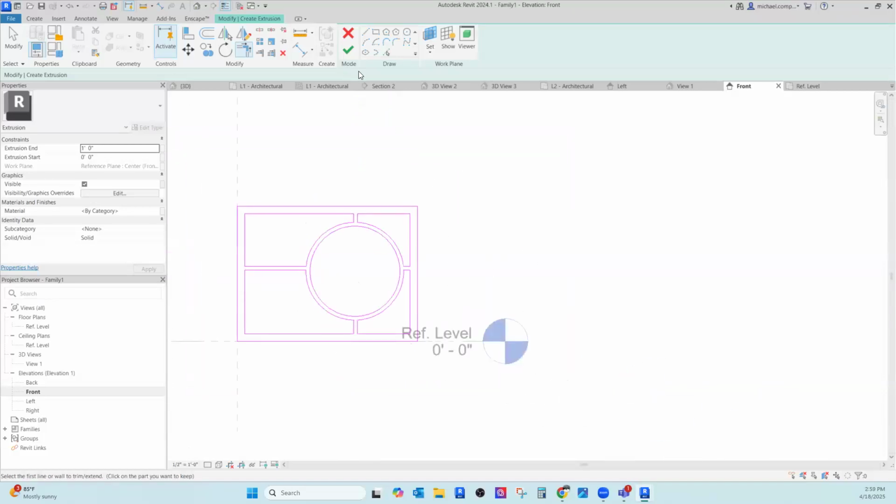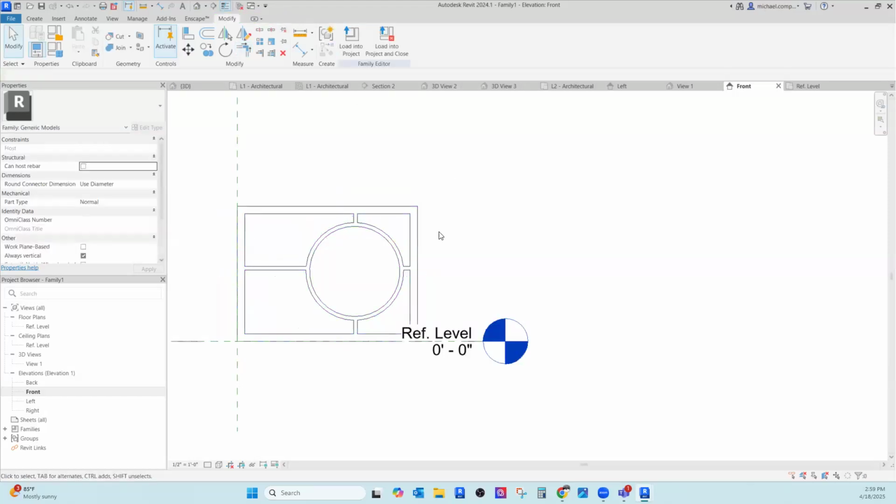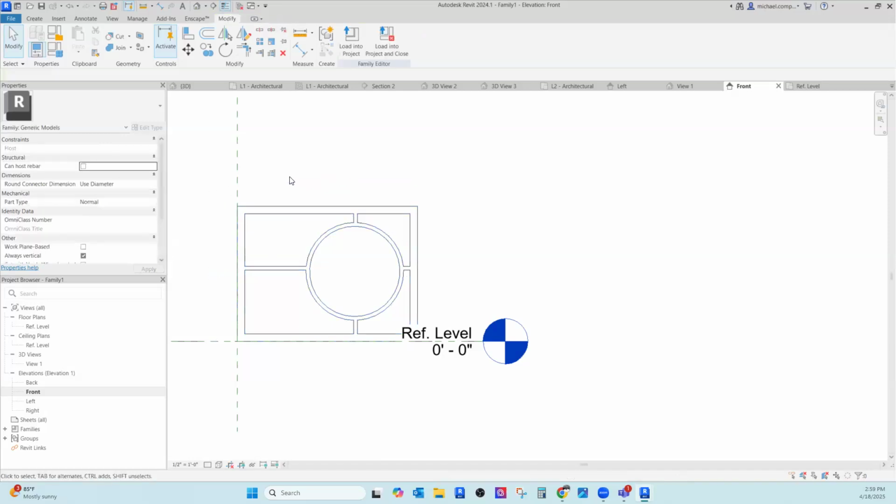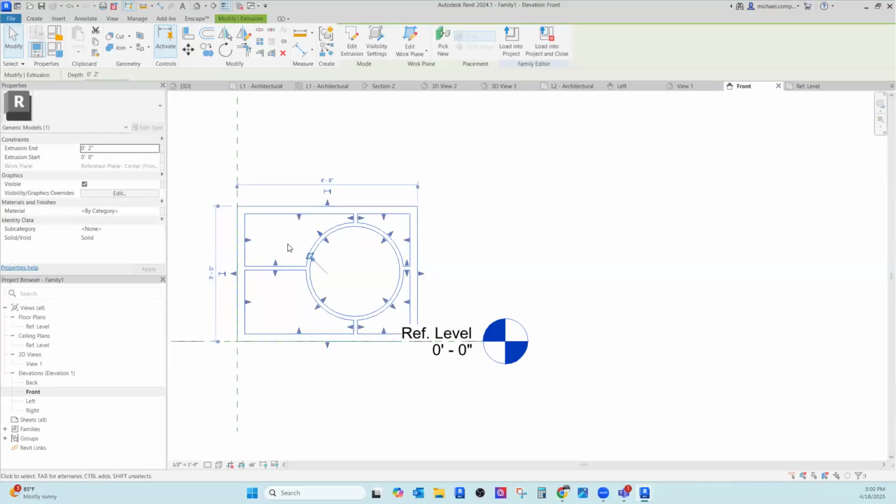Okay. So there's my custom panel, railing panel, right? So hit OK. And that's just the structure of the thing. Now I need the, oh, by the way, what did I say it was? It's not a foot thick, that's for sure. Let's make it 2 inches thick. And then I need the stuff in the middle, right? Because there has to be a different material. You can't have a railing with more than 4-inch separations. So this is going to be metal and glass.